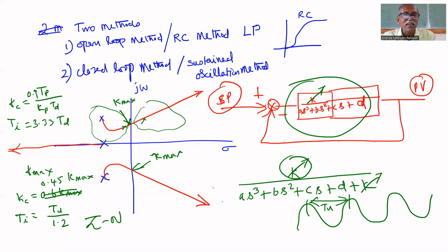They used a 3 to 15 psi signal to transfer measurement. If they measure 100% measurement, they send 15 psi. 0% measurement means 3 psi. 50% means 9 psi. That signal was used in those days. At that time, the PID controller could be tuned by using these two formulas. They gave the thumb rule.